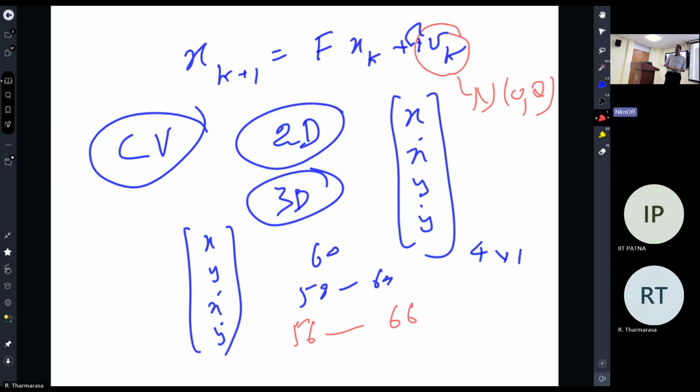Okay, let's say for both of them, vehicle and pedestrian, we use a constant velocity model. We decided that because that's an easier problem, an easier way to write the code. If you write the code, IMM is good, but it's harder to implement, right? Sometimes even I take a lazy shortcut and always use constant velocity. But anyway, even if you use IMM, there are several problems. But let's assume we use a constant velocity.